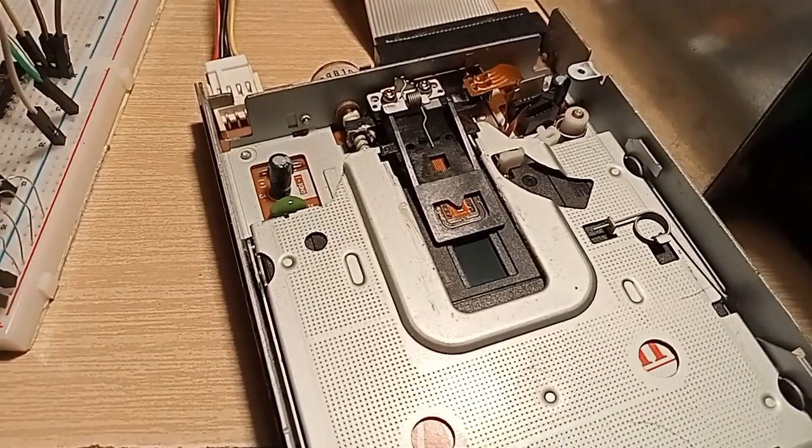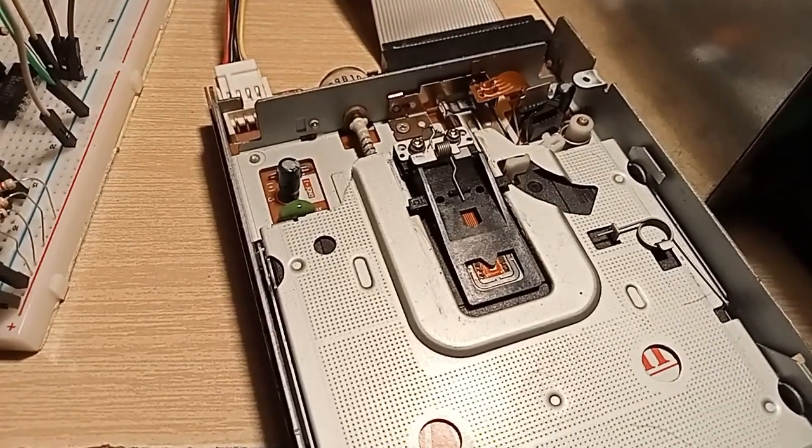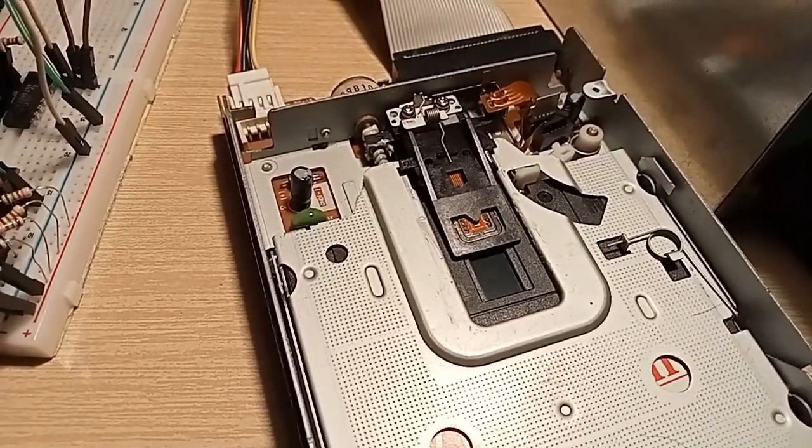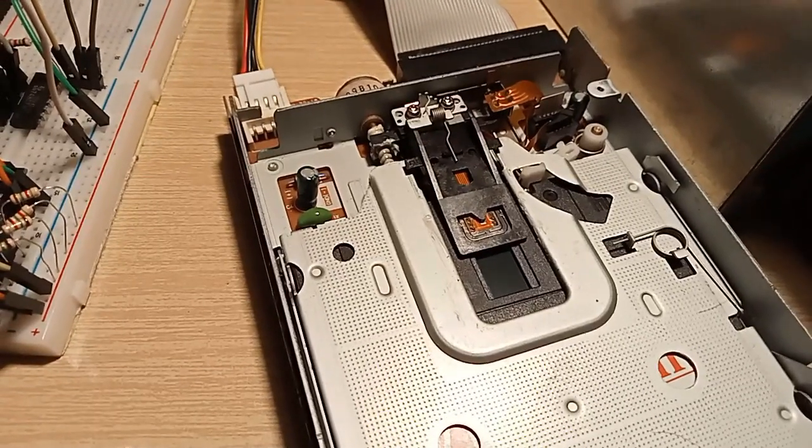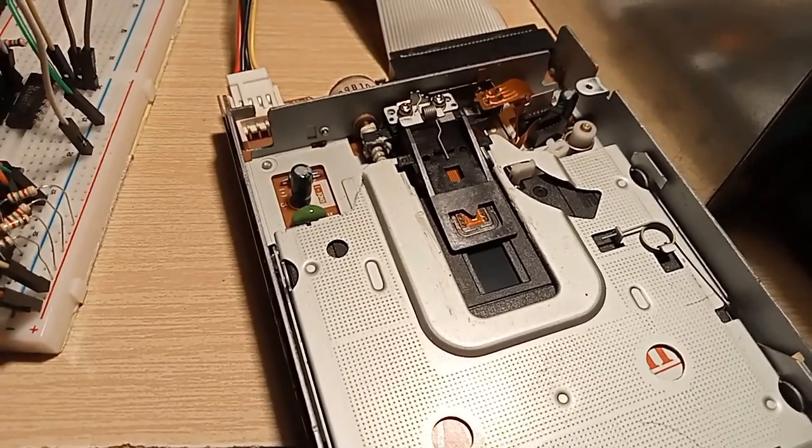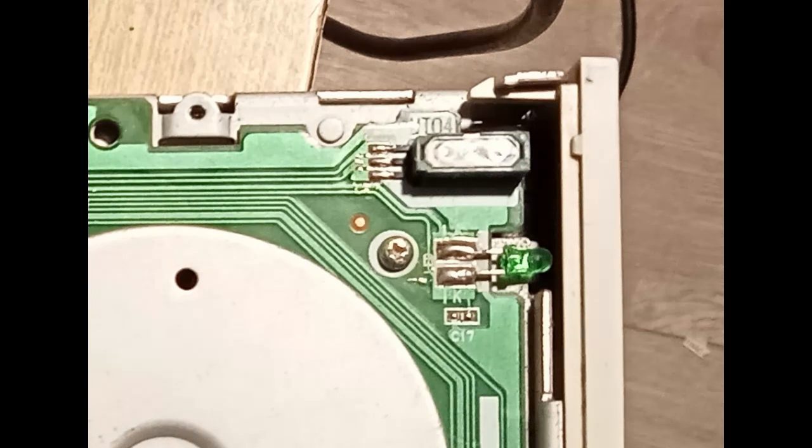The stepper motor allows moving the heads beyond track 79. Some floppy disks have track number 80, which is possible to read manually, as a simple copy protection mechanism. Write protection is done by a simple switch, which detects the tab's position in the floppy disk. Based on that, write is allowed or not.